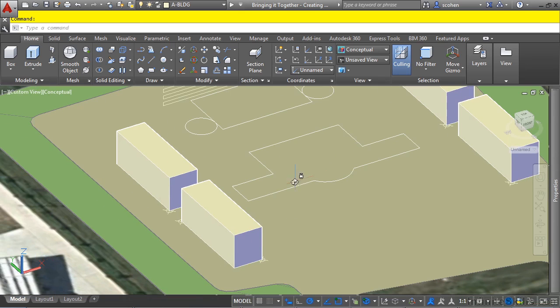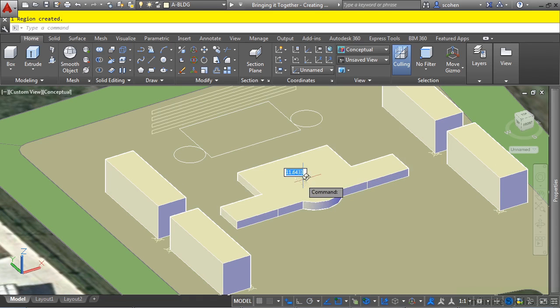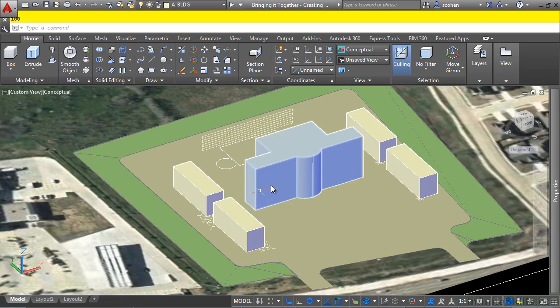Now let's go ahead and press pull our main office building using the shortcut Control Shift E. As soon as you hover, it'll highlight the boundary within where your cursor is, and then simply left click. You're immediately prompted for the height. For the height, let's go ahead and type in 100 and then press enter. And there's our initial office building.